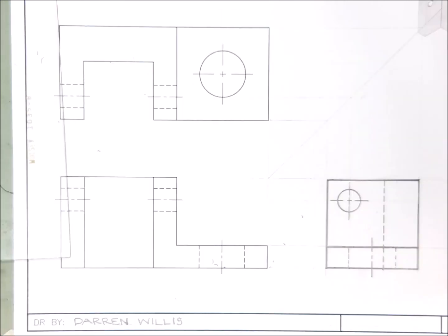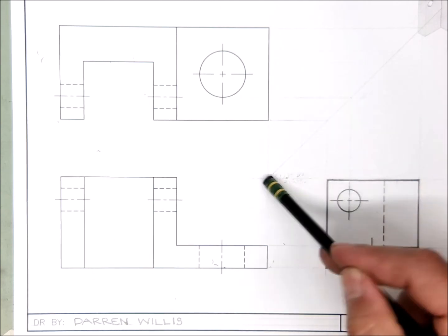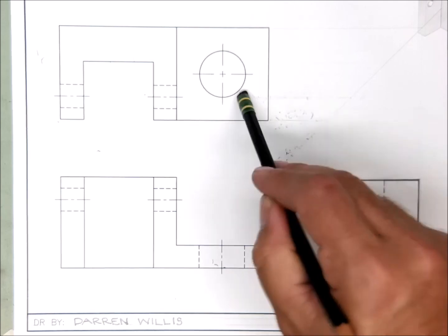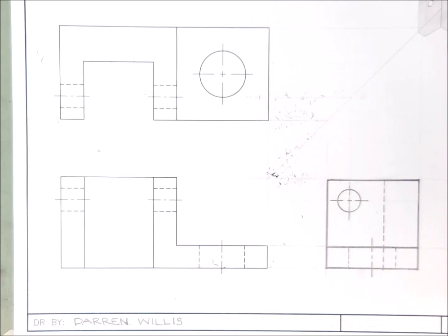You'll save yourself the loss of some points if you could check out a couple of things before you say the drawing is completely finished. Number one, is everything erased that should not be there? Right? If lines are too dark, projection lines are too dark, they need to go away. Are all the elements that are supposed to be there included? And then is everything sufficiently dark enough? Are all the object lines dark and dense all the way through? So if your line goes from dark to light to dark to light, or light to dark, or has skips, then that's not very good. You need to fix that up.